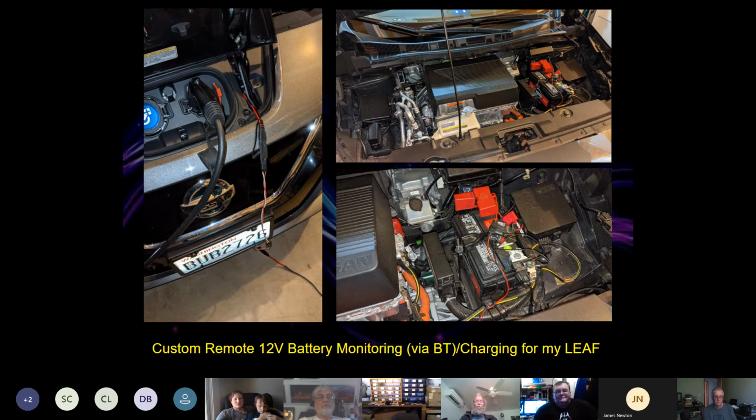Right. So for 99.99%, or some large percentage of people, when they're plugging in their car to charge it, the 12-volt battery is fully charged. And by the time that's self-drained enough, their traction battery is fully charged and the AC's been taken away. So there is no power there to charge the 12-volt battery. There isn't really a good reason to spend the money to put another charge controller for the 12-volt battery off of that line. I mean, for your situation, you could solve it.